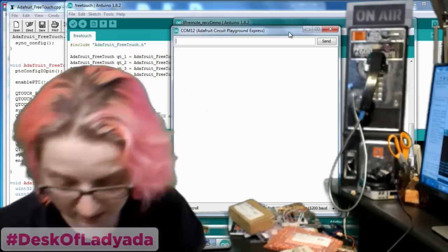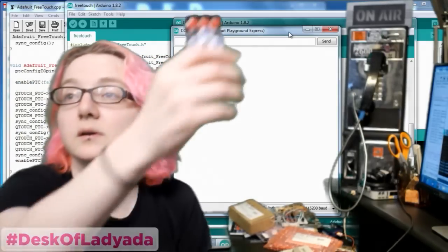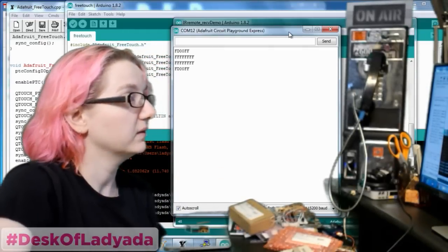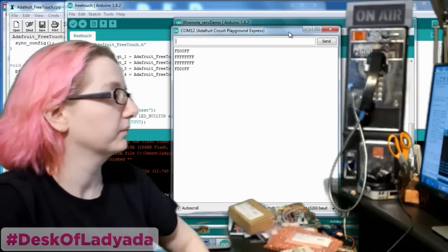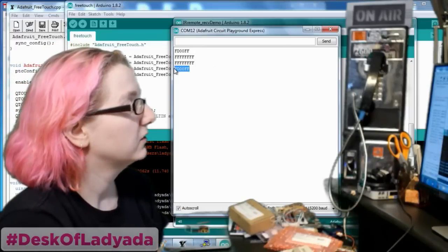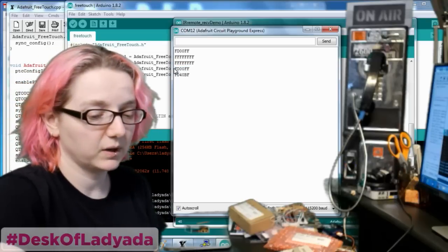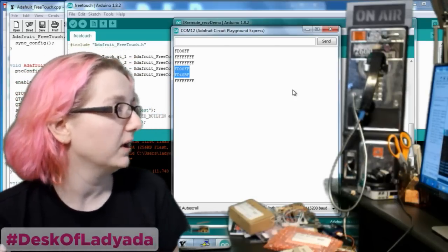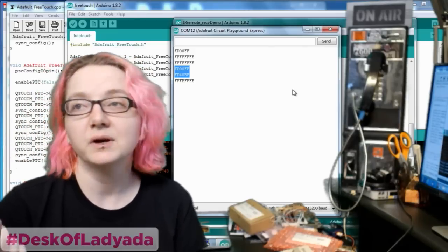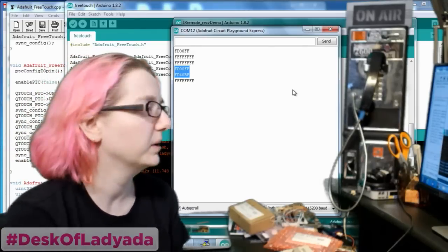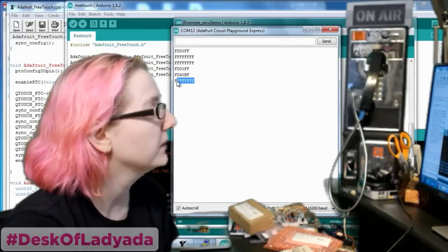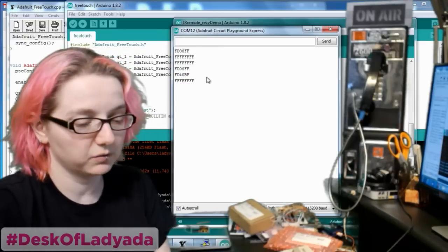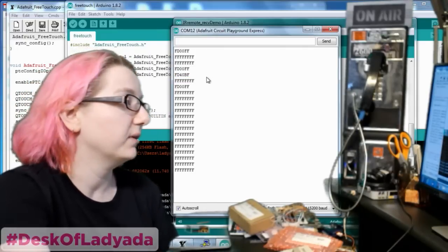So I've got my remote control, my little happy friendly remote. Let's try this. You can see it's printing out the different codes. This is the volume down code, and when I press red, it's the volume up code. These are the 2 codes you get, FD00FF, FD40BF. Even though these are 32-bit, you only really get 24 bits. I guess they just use the rest of them, or they're zeroed out. And if you repeat a code, if you hold down a button, you'll get FFFF. That's the repeat code.